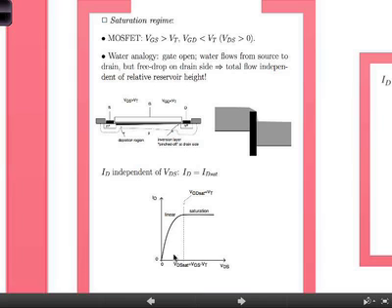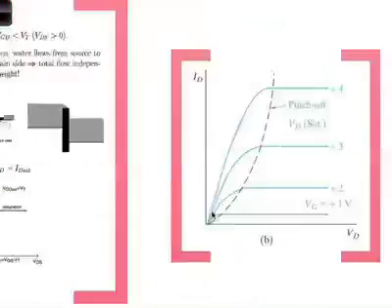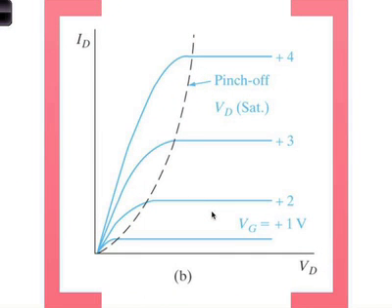So in the current voltage curve, you have something which goes up. Now this is the linear regime, and out here you get saturation. As drain voltage increases, nothing happens to the current. Same as what we had for the JFET. Okay? So three regimes. You have cutoff, linear regime, saturation. Now we have to see what that means physically.